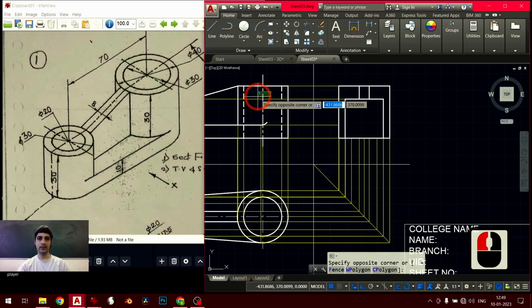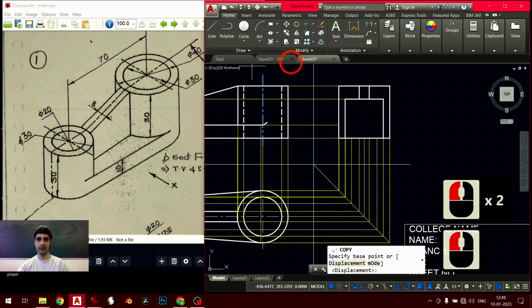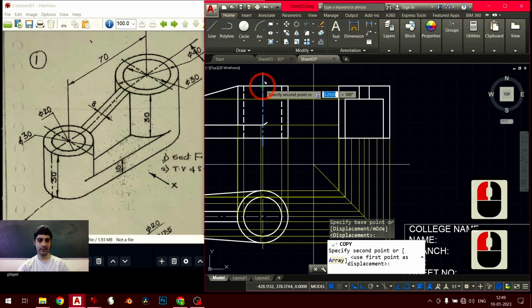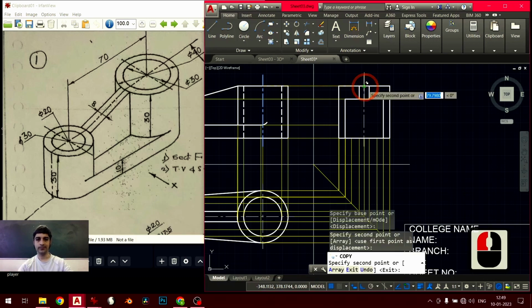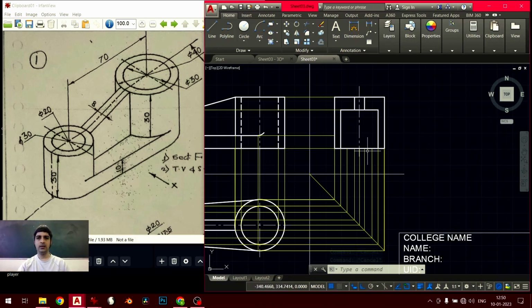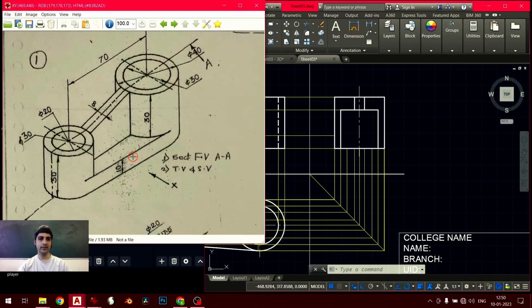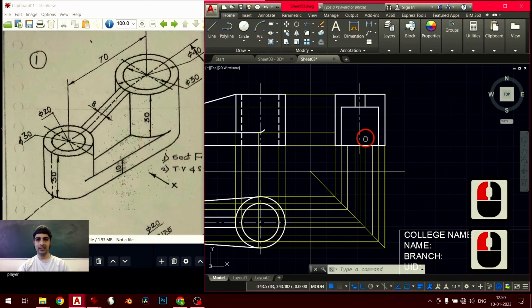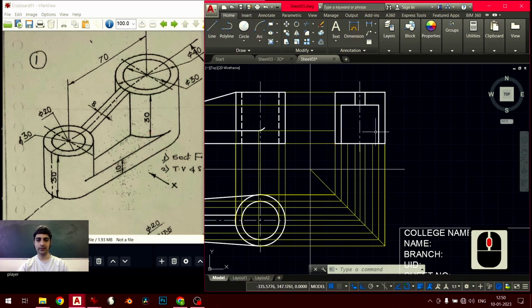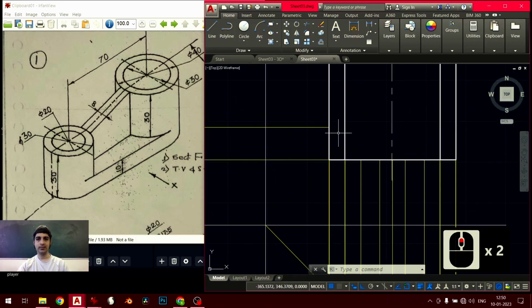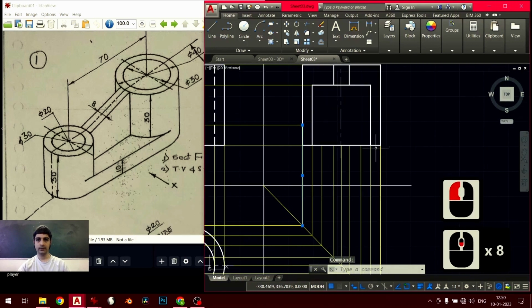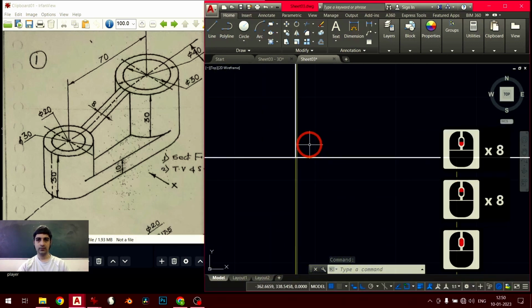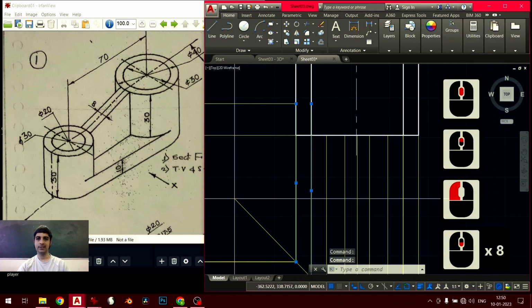But before I do that, I'm just going to make this center line to just make sure everything is conforming properly. And I'm not even going to make it, in fact. I'll just snap this copy here. So then we'll start worrying about the other things that are visible, specifically this base plate. So for that, I see an edge formed here horizontally and here as well. And it'll be projected between these endpoints that I've figured out. So one over here, and then this inner one, and the same ones on the other side.